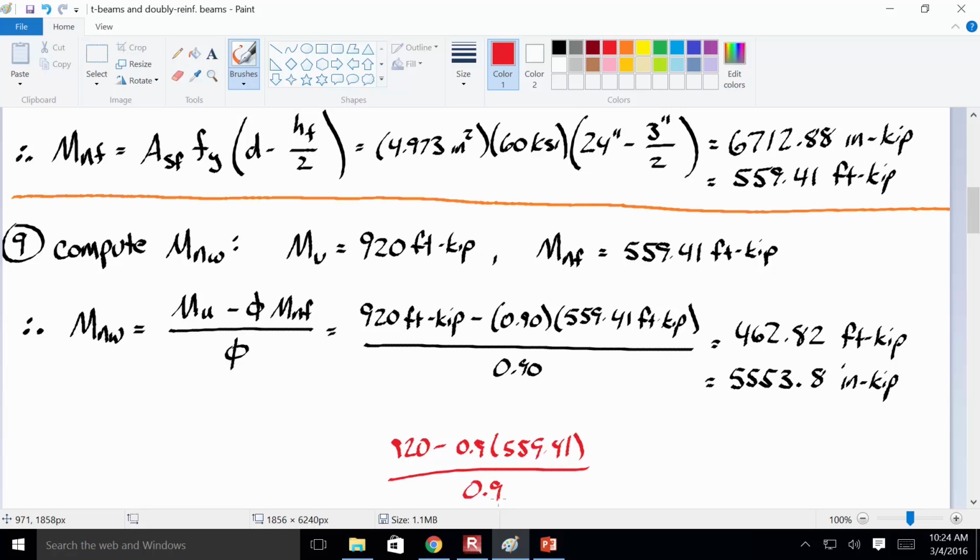So I'm sure that some of you are probably looking at this and going, well, couldn't you have just multiplied this by 12 and gotten inch kips in the end and used that value instead of this? It doesn't matter what you do as long as your units are consistent, okay? You can argue that there are probably different or better ways to do this, and that's fine, but notice how in every calculation I'm doing, inches squared, KSI, inches and inches. So I know what my answer is in the end. Does that make sense? Whatever you do, it doesn't matter. Just make sure that you're consistent.